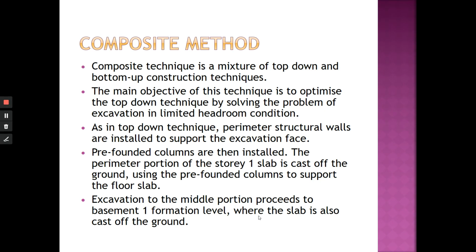Okay, the last method is the composite method. Composite means mixture. Okay, composite technique is a mixture of top-down and bottom-up construction techniques. The main objective of this technique is to optimize the top-down technique by solving the problem of excavation in limited headroom condition.